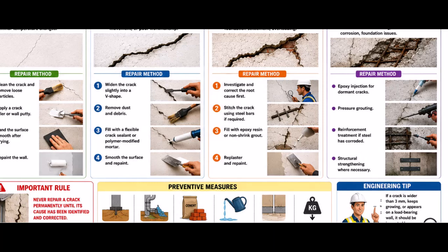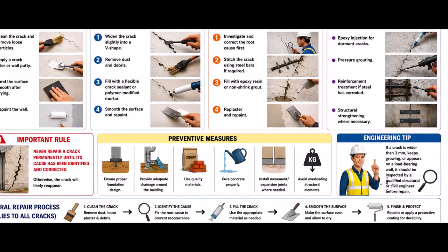There's an important rule for us to know when it comes to cracks, and that rule is this: never repair a crack permanently until its cause has been identified and corrected. Otherwise, the crack will likely reappear.